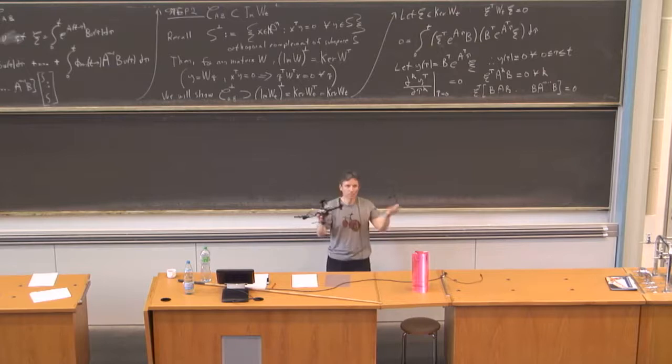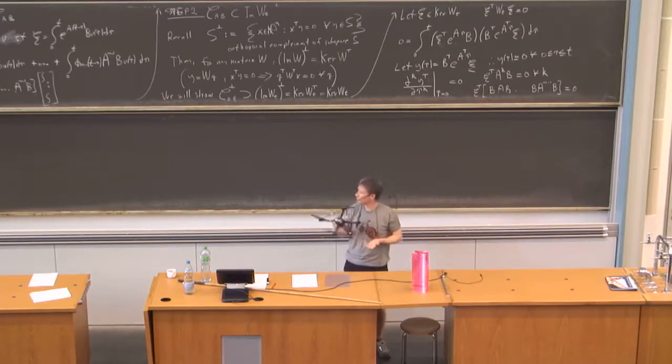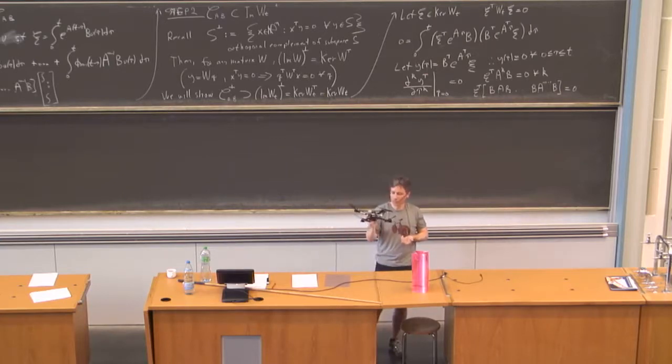Now, you guys understand this stuff. It's pretty obvious to you, especially if we just follow this lecture, that just because I only have 4 control inputs doesn't mean that I can only control a system with 4 states. This has 12 states: 3 translational positions, 3 orientations, and their derivatives. So I have a total of 12 states, and I can completely control them with 4 actuators.